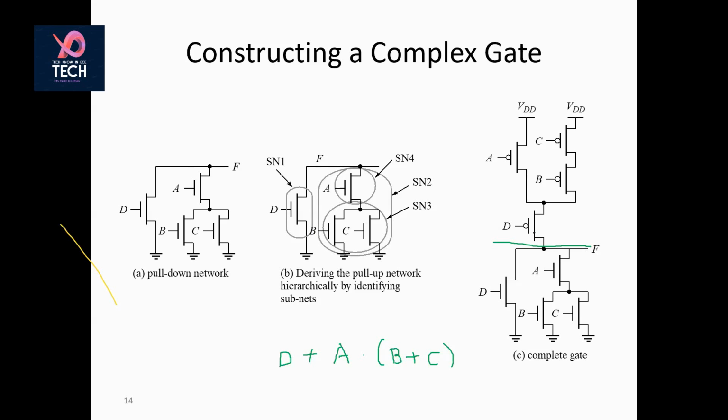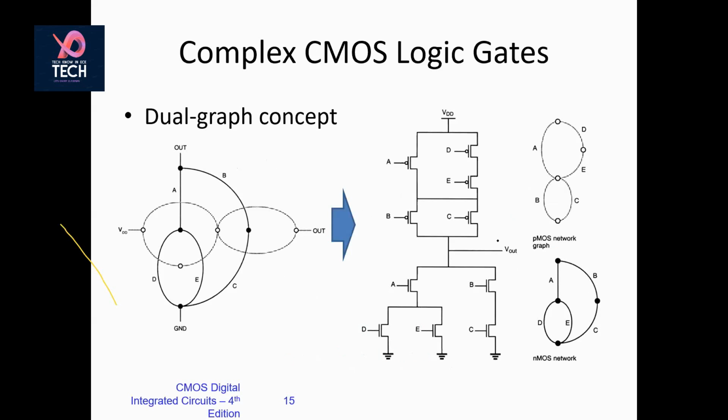So from here you can easily see that here you are having 4 inputs. So how many transistors are required? 8 number of transistors are required. So that means we are actually, okay, this is the one which we are talking about. So this is the expression actually here. So now they are in series, so they become parallel. So they are in parallel, they become series. So the thumb rule remains same, that most activity in case of PMOS should be near the VDD, in case of NMOS should be near the ground, and rest other things remain same.